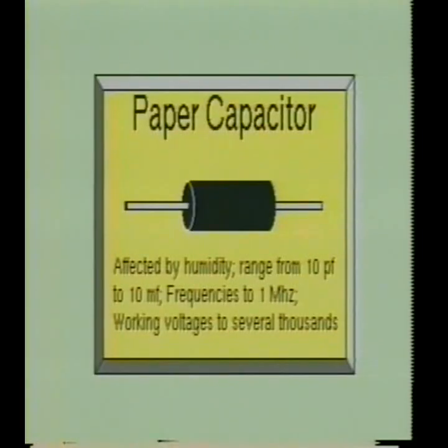This is a paper capacitor. It has fairly low leakage when new, but has a tendency to form moisture inside, which causes the leakage to become very high. It is available in sizes ranging from 10 picofarad to about 10 microfarad.